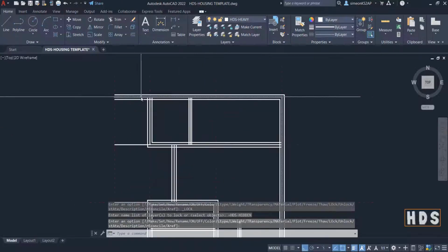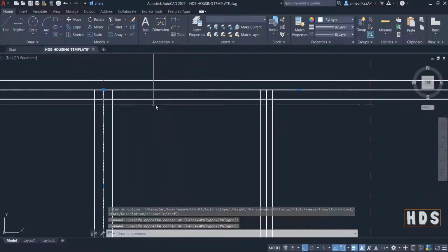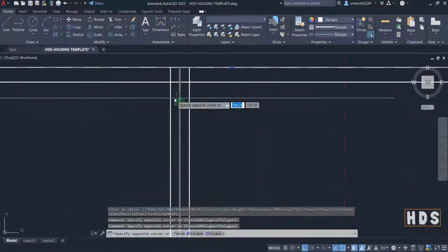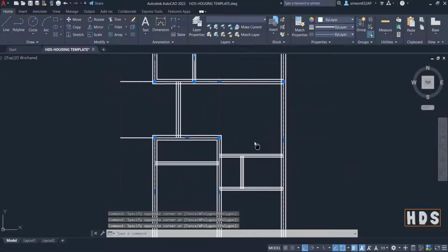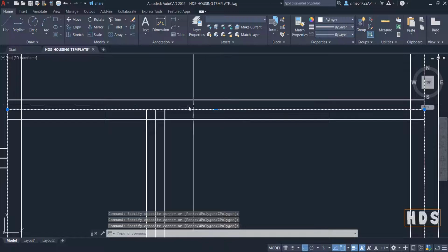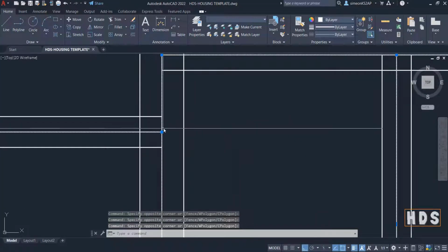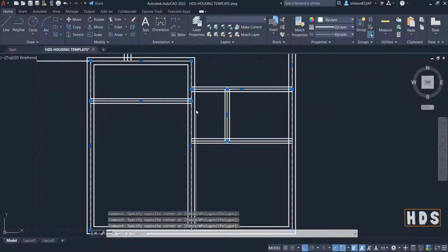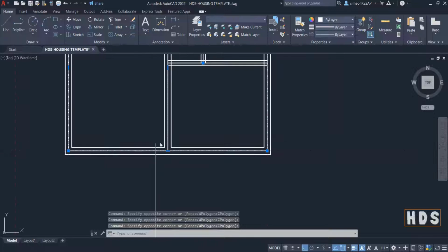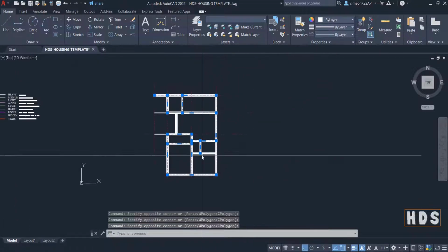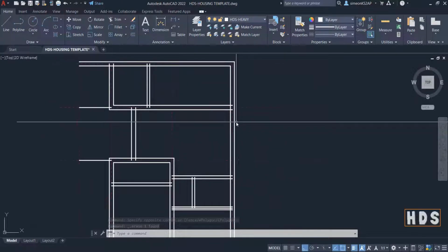That means that we will not be able to delete or to move them. Now go to that internal polylines, and we are going to delete all of them. Yes, we are going to delete all of them. That is actually good. Delete. Now we remain with a particular polylines.